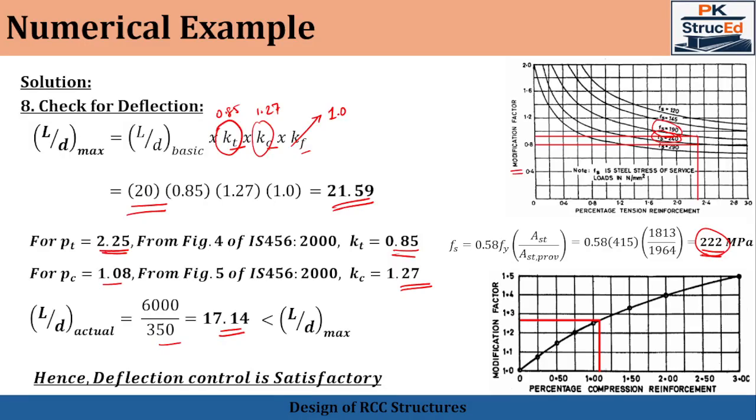So let us summarize today's lecture. Doubly reinforced beams are used when the depth is restricted. Here, the compression steel increases the moment capacity as well as ductility. Design is similar to that of singly reinforced beams, involving flexure, shear as well as deflection checks. These types of beams are common in continuous beams, bridges or heavy load carrying structures.